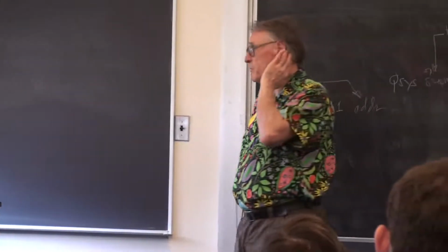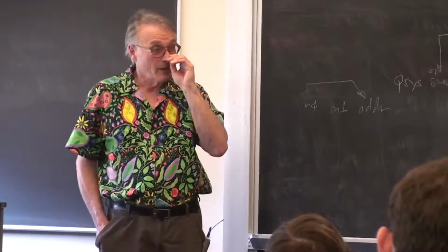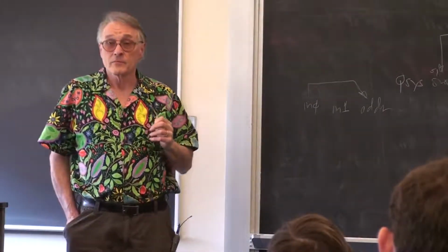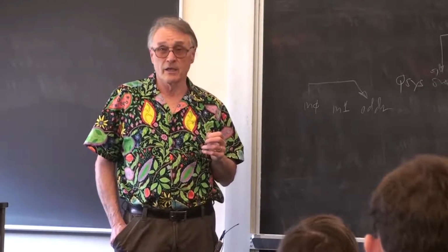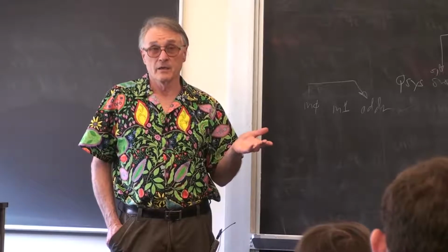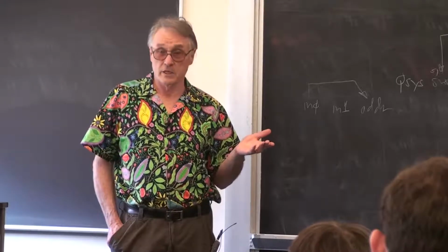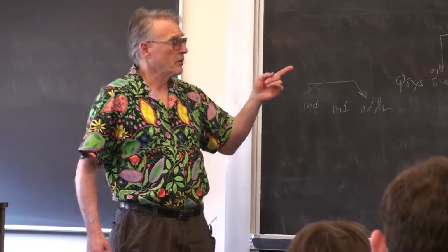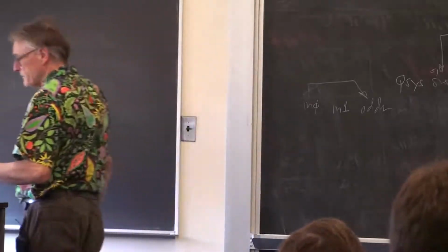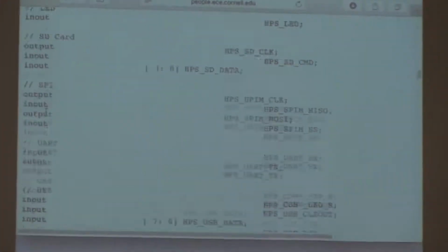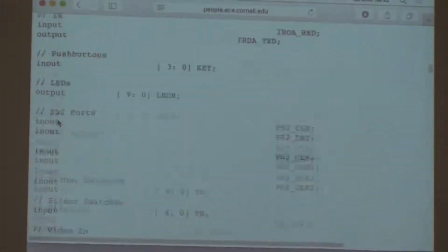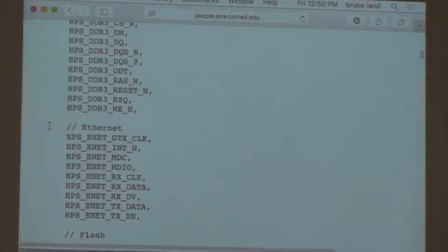You're probably going to render it into SDRAM or into whatever default RAM is running the VGA controller that you're using. This version of the code that handles the memory not only has floating point in it, it has a modified video controller that uses only SDRAM.